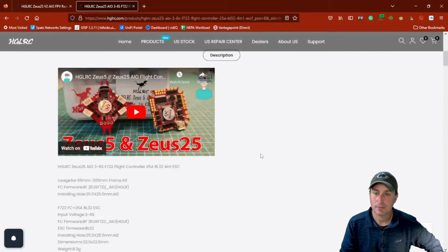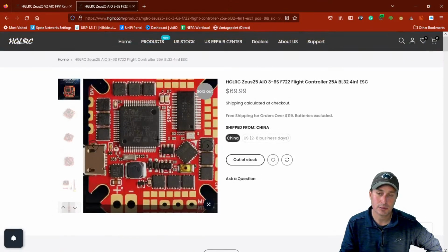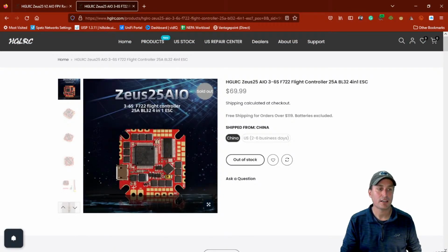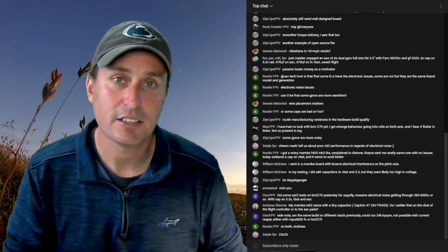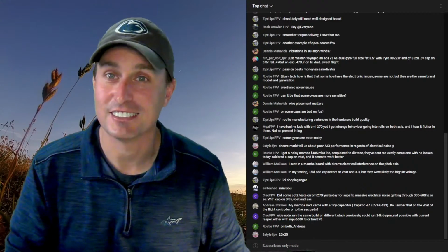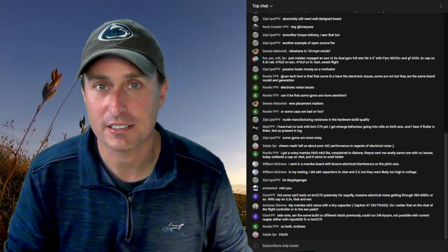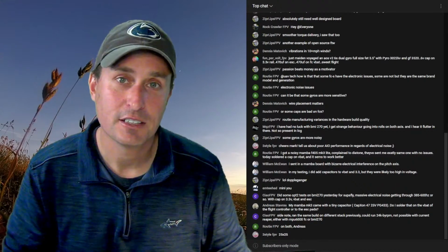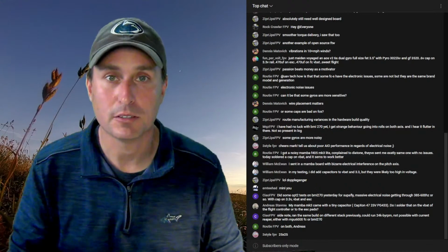And then I tuned up the Betaflight one, which had issues as well. The one thing I changed on it is that initially when I received this quad, he had the ESC PWM frequency set at 24. I think he actually had it at 16 kilohertz, which is a little crazy. But at 24 kilohertz, he had it set at. And again, this is a 3.5-inch quad. I changed that up to 48 kilohertz, and that made a big difference. It didn't have the electrical issue.